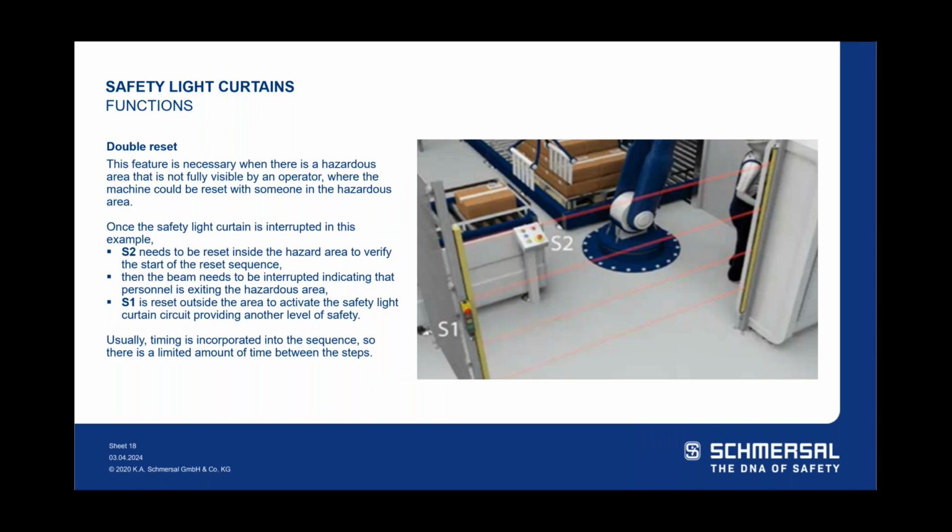The last function we have is double reset. And again, this has become really common with these large robot cells. You're seeing cells now that sometimes have multiple robots in them, so they're large cells. And maybe they have one opening where they have a light curtain. Operators need to go in there, maybe a forklift needs to go in there, but there's room inside that cell for somebody to get lost.